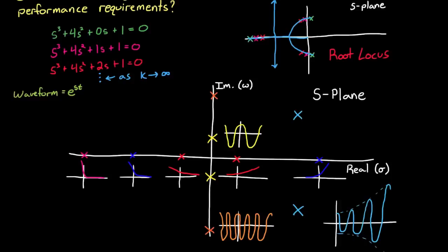Even though both poles and zeros of a system are needed to characterize the response to a forced input, only the poles of the system are needed to dictate an unforced response to a set of initial conditions. And this ties directly to the stability of a system.